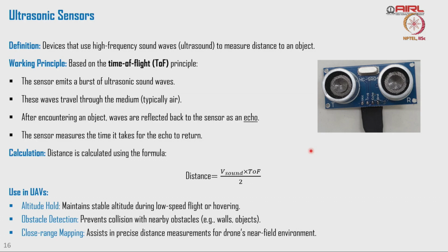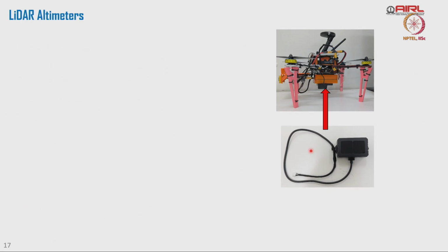The problem is the characteristics of ultrasonic sensors affect the conversion of the distance to velocity measurements. We need to take that into account, and it is not for long range. So we need to use it for short range obstacle detection, and it can only give you point measurements. It does not tell you how big the obstacle is, right. So generating a path for that becomes a little tricky.